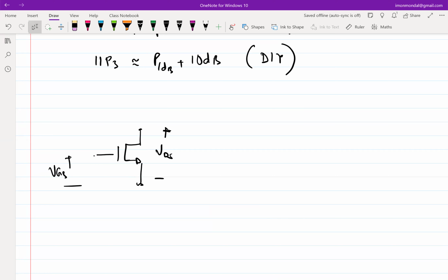It's in fact quite complicated. If you plot against VGS and do a Taylor series fit, or keep differentiating with double, triple differentials, you will see that you never get a zero. If you never get a zero, all the derivatives exist, which means it's definitely not a square law.